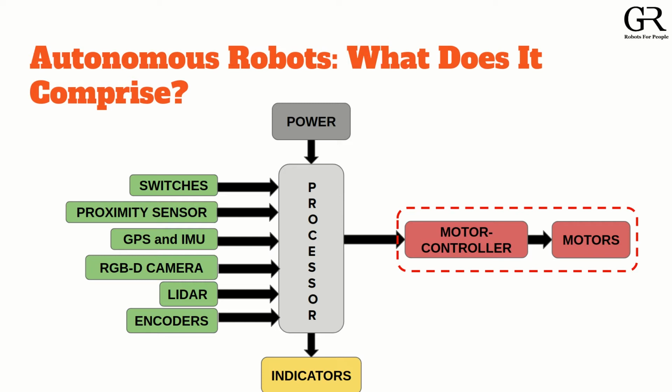The next one is the lidar. Lidar is nothing but a 360-degree scan around your robot. It's a single slice plane across your robot, so you can get a clear view, and it is very useful to build a map of the surroundings of a robot.